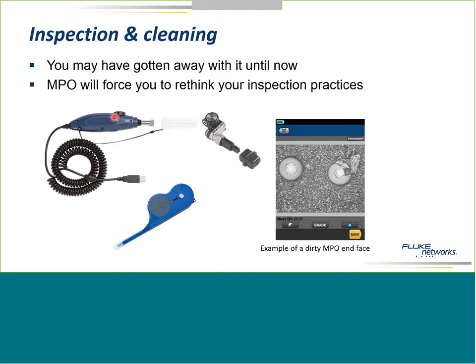Now, what we're seeing here is a camera, and here's a tip that we can put on the end of the camera so we can get this great image. This is the background, the composite material in the connector, and here we're seeing 2 fibers. These look like 50 micron multimode fibers. This one has some type of oily contaminant here around the core of the fiber. Here's a piece of dust that we have.